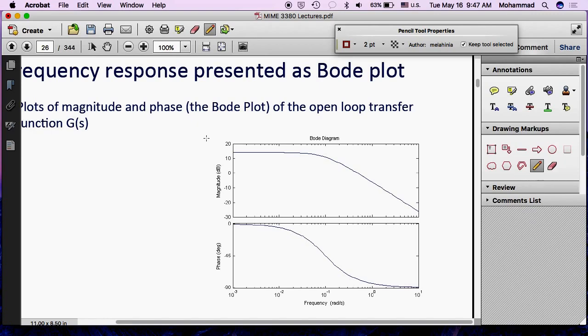The fact that this drops down, let me write here, this is the ratio of output over input in log 10 scale. Multiplied by 20, that's the meaning of decibel. So if you forget that this is decibel, this is the ratio of output over input. So up to a certain frequency, that ratio is consistent. And after a certain frequency, it significantly diminishes, so you don't get as much output.